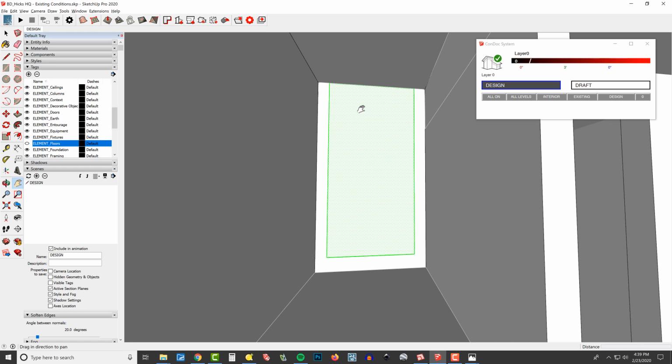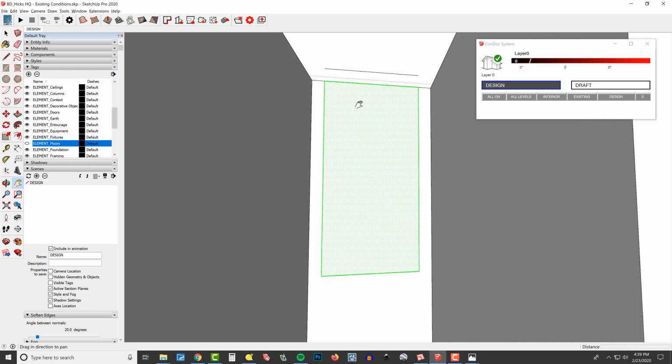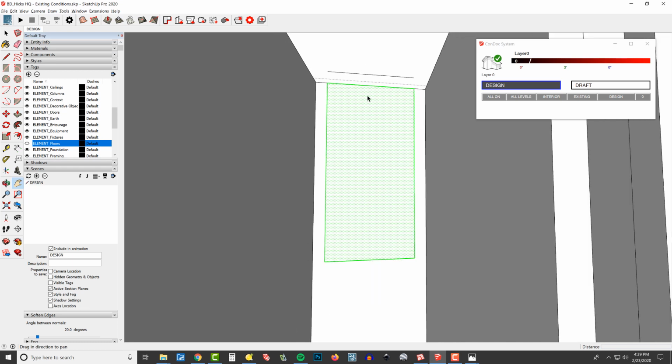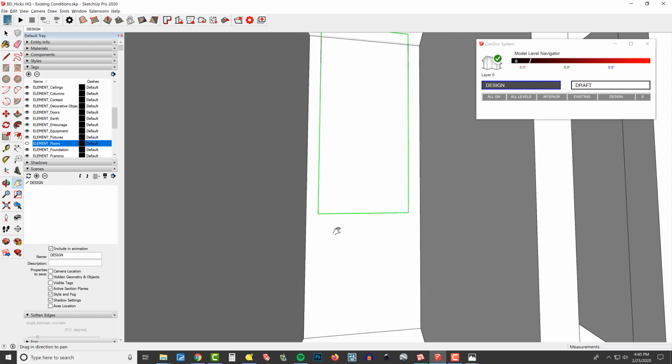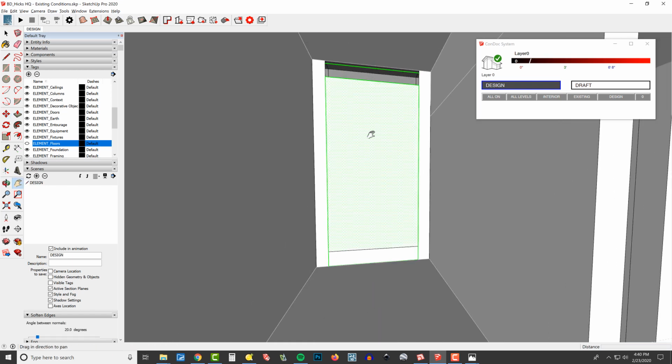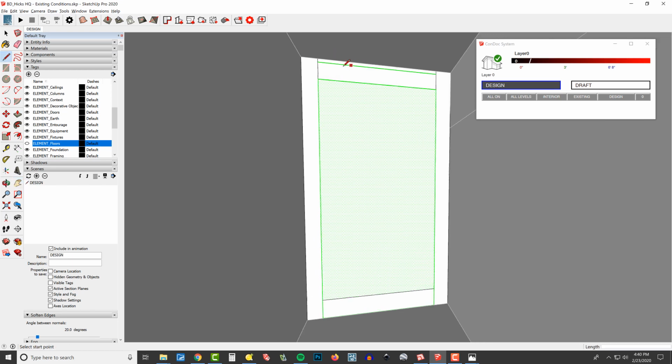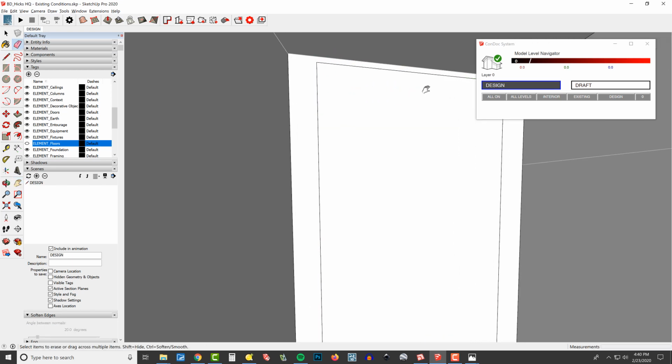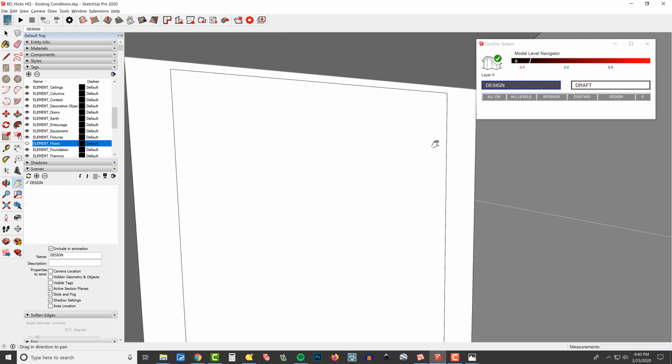Beware. If you want to get around that, you can just take this whole thing and group it, and then when it's grouped, you can move it. It's going to leave behind a little bit of funkiness, but I can just explode it again, and then draw some lines in, kind of reheal that geometry, like that. That is working out the way I want it to be.